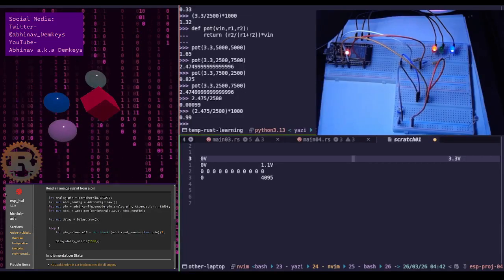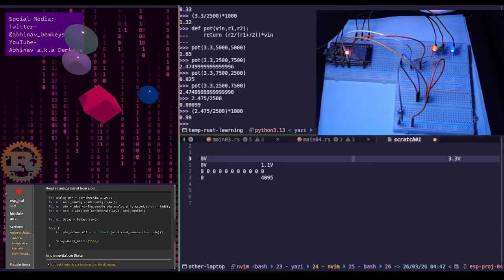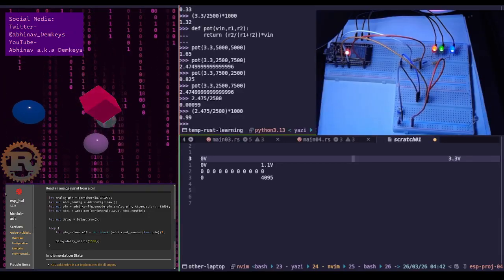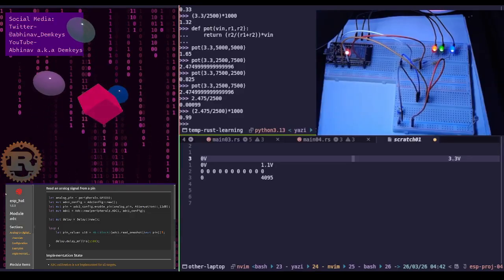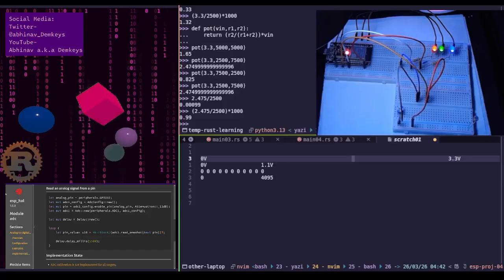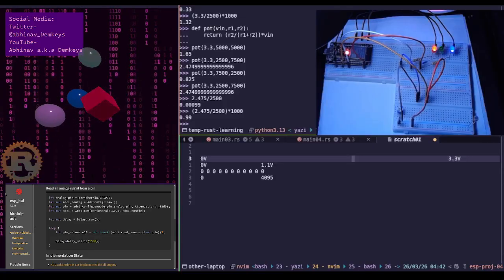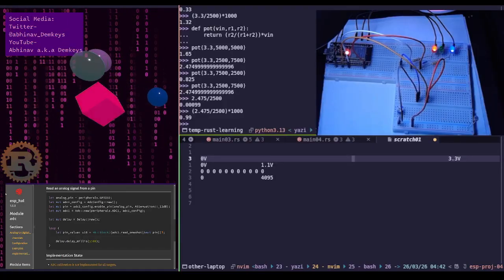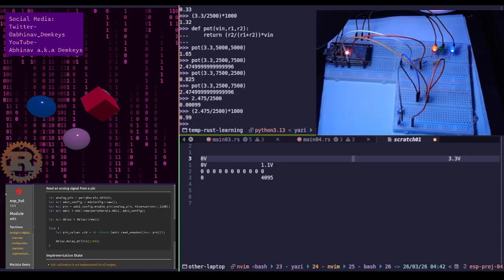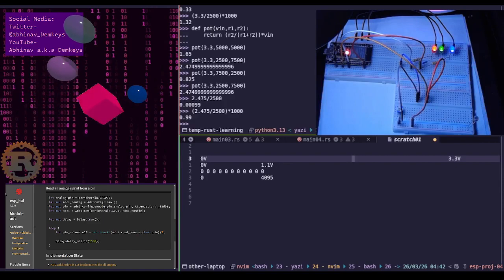Fortunately, an ADC pin is high impedance. Think of the ADC pin like a person holding a voltmeter against a wire. The person isn't consuming the electricity, they are just looking at the pressure. Internally, the ADC has a very high resistance, typically in the mega ohm range. According to Ohm's law, because R is massive.